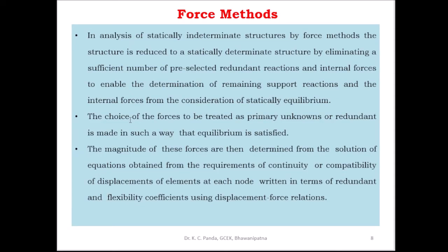First coming to the force method. In analysis of statically indeterminate structures by the force method, the structure is reduced to a statically determinate structure by eliminating a sufficient number of pre-selected redundant reactions and internal forces, to enable the determination of the remaining support reactions and internal forces from the consideration of static equilibrium.